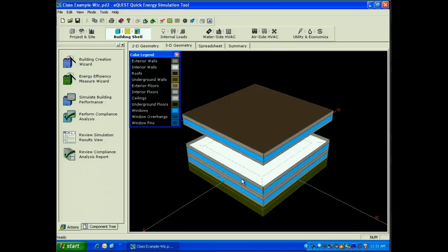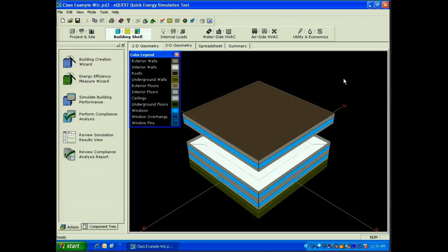We'll get into some more things in this view. Actually, I do want to do it now. Sometimes when you get into this 3D view, you can't see the picture. And there are a number of things that you can try to get the picture to show up. One is if you right-click on the black background, the first option there is Reset Camera. Usually selecting Reset Camera will make the image appear on here.